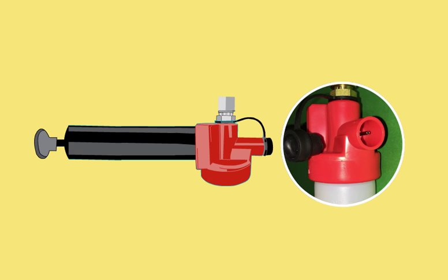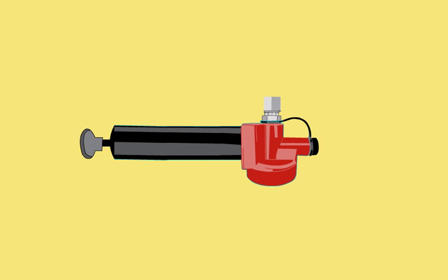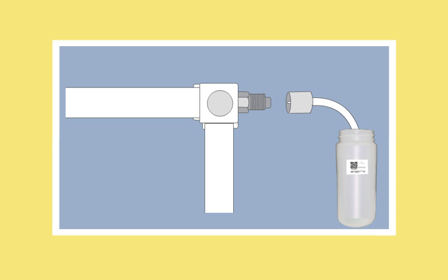To pull a sample from here, you need the engine to be running, so you're pulling from a live stream of fluid. This best represents what is flowing around the engine. Of course, not all engines will have sample valves, so this depends on your fleet's engine specifications.